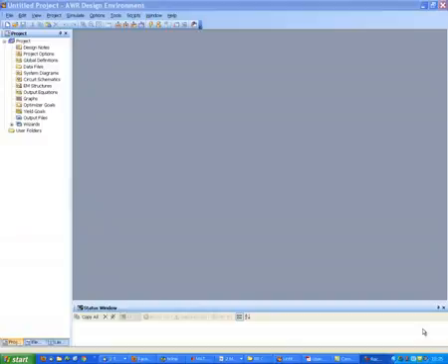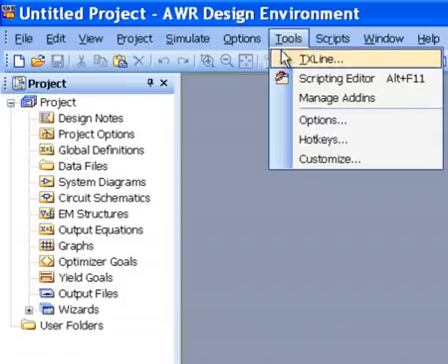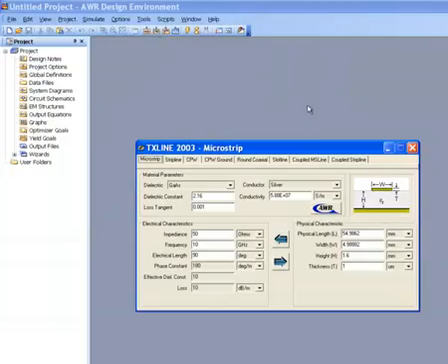it particularly useful. So to actually design a line, we can use the equations that are given in the notes, and those would work to some extent, and they're quite approximate as is specified in the notes. But we can also use a very useful tool in Microstrip Office called TX-Line. To get it, we just need to click on Tools and then TX-Line.